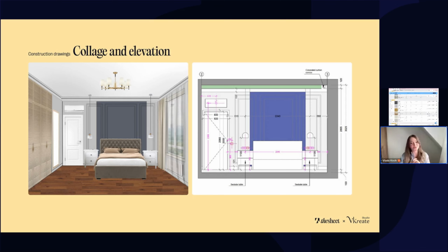If you're not that lucky, your room would have more walls, and you have to do elevation of each of the walls. I also like to always put my electric details in another color. So here you can see I always use pink for electric. So the electricians, when they're on site, when they have my drawings in their hand, they could directly determine where the connections they need to make on site.